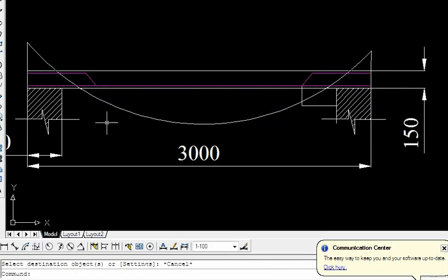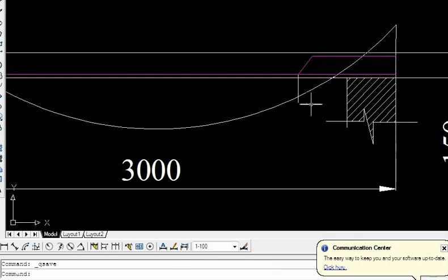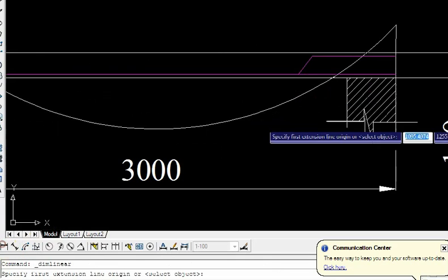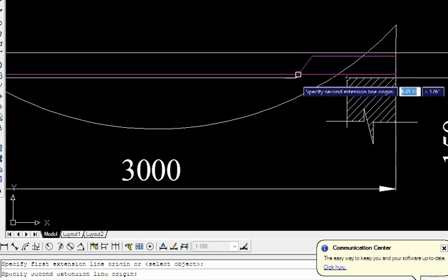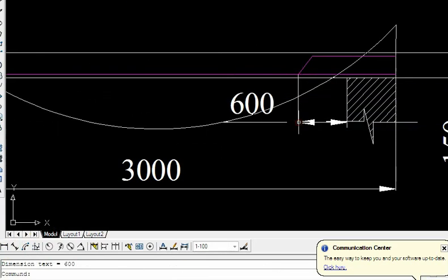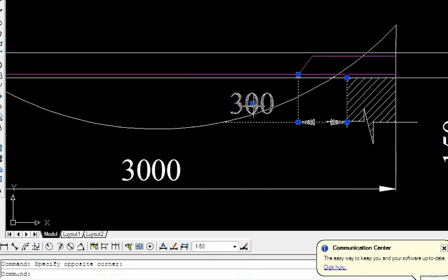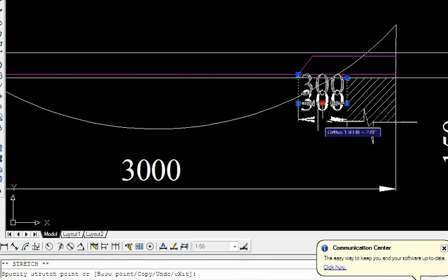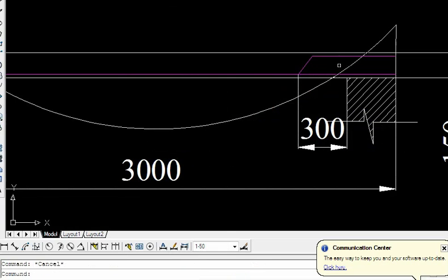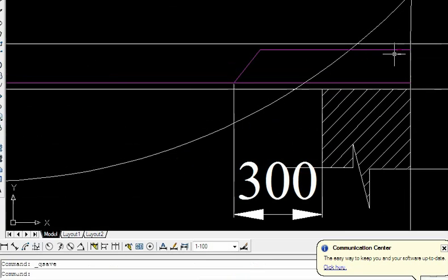See, this is what the main bar reinforcement is given. We can see here at a distance of 300 from the edge, meaning the thickness minimum D we take, but here I am taking 3. Why? From these dimensions, at a distance of 3 from the support, the bar gets bent here. We will bend the bar here and take it to the top side, where since the negative moment is there at the end supports, the main bars are given at the support point at the top.